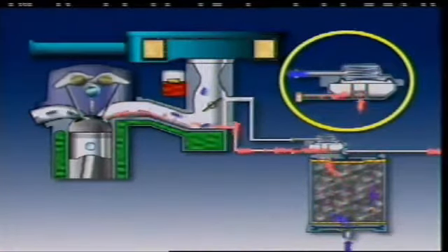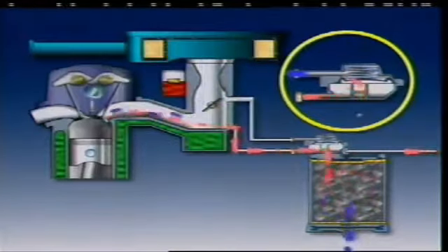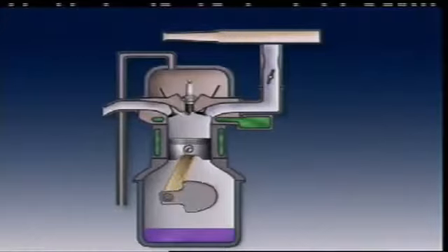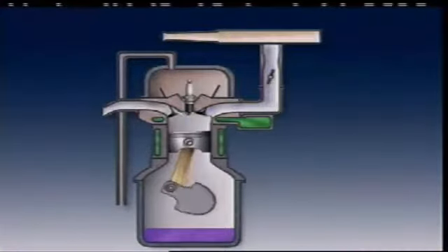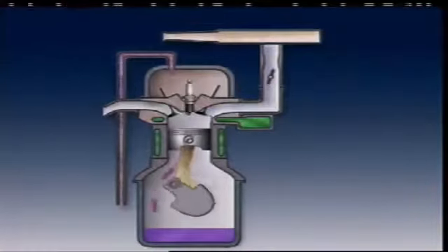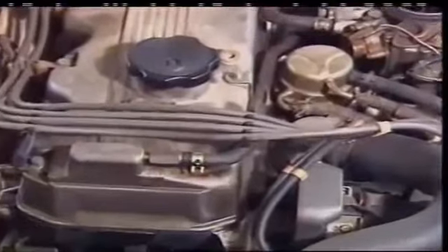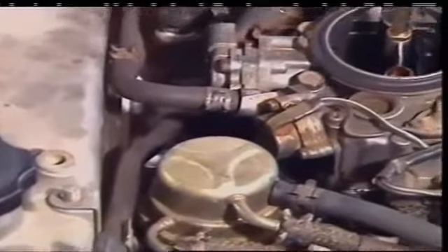In a petrol engine vehicle, during an engine cycle, some of the gases escape past the piston rings into the crankcase. This is called blow-by. Some of these blow-by gases mix with heated vaporized oil and can usually escape out into the atmosphere. Modern vehicles direct these gases and vapors back through the inlet system to be burned during normal combustion.